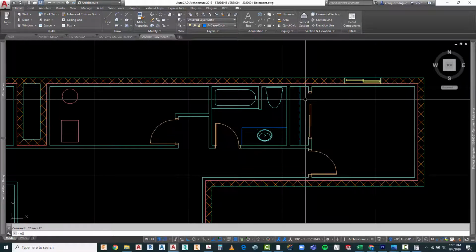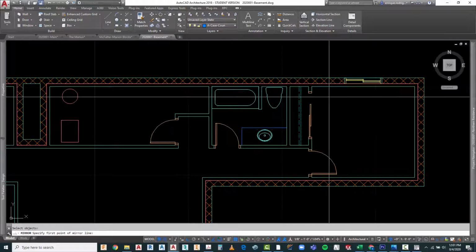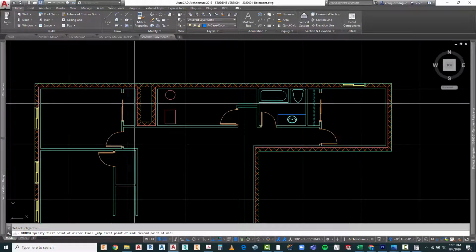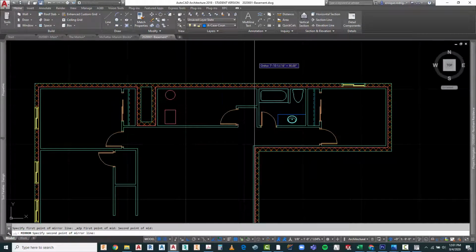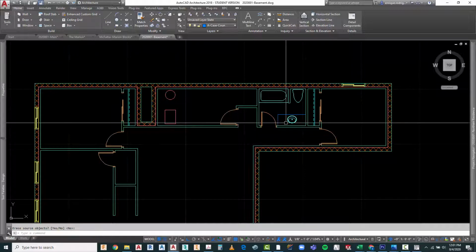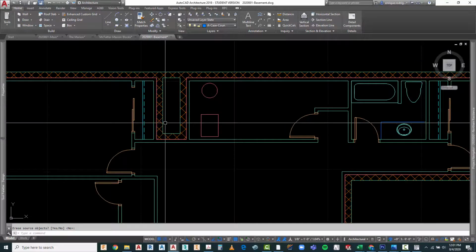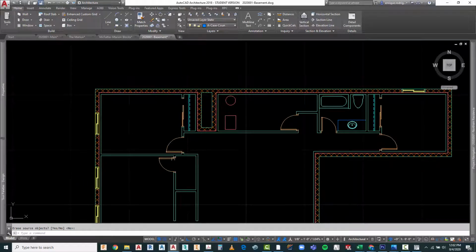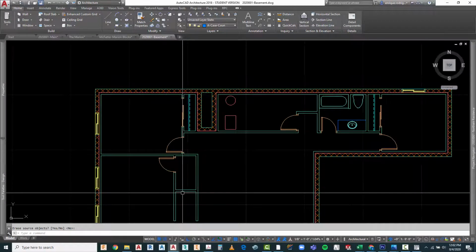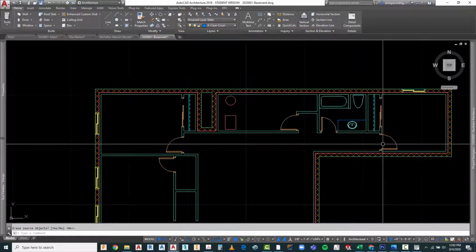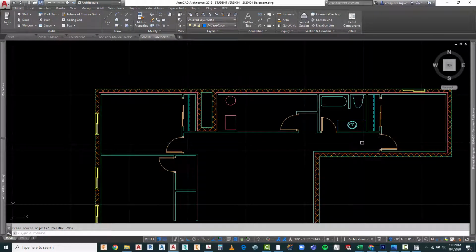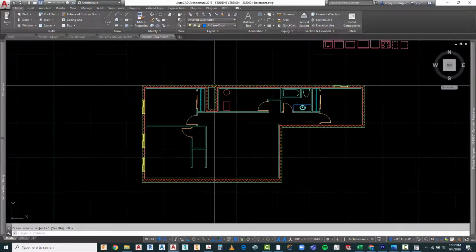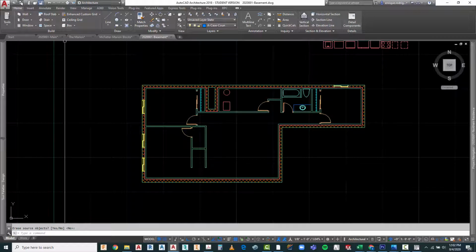And I could probably just mirror this. I mirror it using mid between 2 points from this wall and this wall. Bring it up, hit enter, and it came right into place where it's supposed to. All right, everything looks good. We've got that door, this wall we're going to locate. We've got a nice door there and here with enough access into it. Okay, let's see what else we can make some modifications in here. All right, let's go ahead and save this.